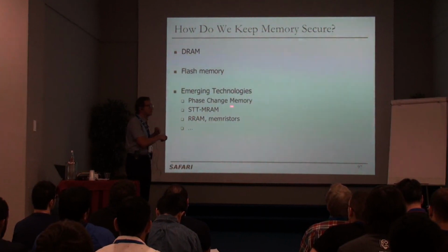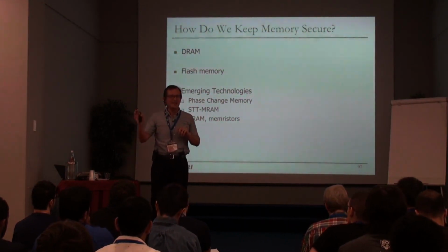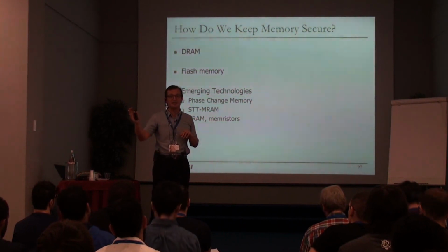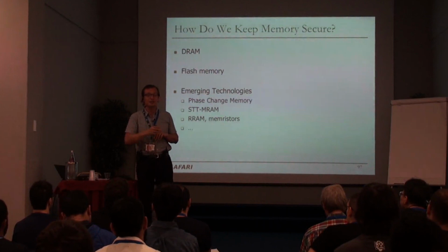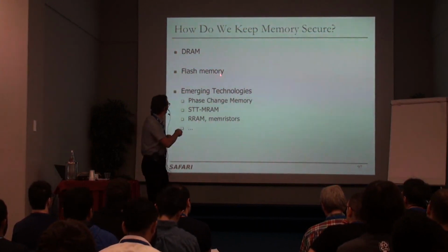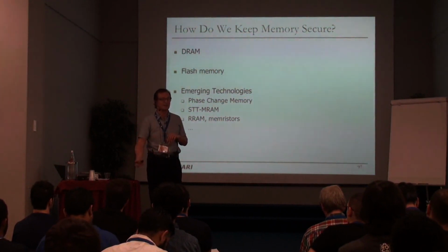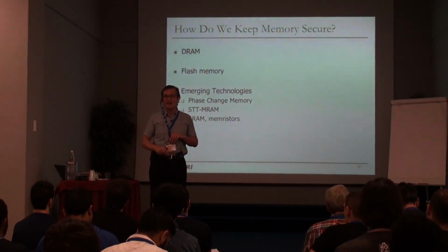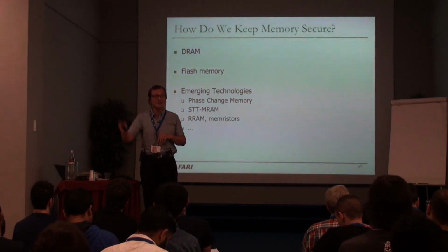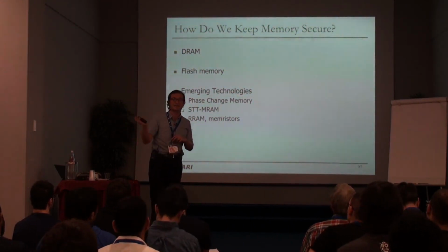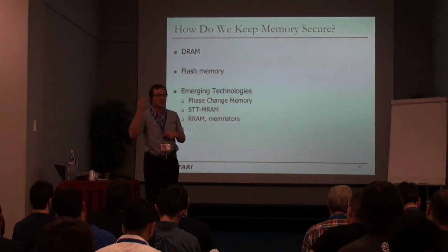You can say, oh, I don't need to refresh phase change memory. Think again. Actually, these are resistive memories, and resistance shifts over time. As a result, you actually need to refresh. Flash, very similar. It loses charge as the flash cells wear out. You need to refresh. And as flash becomes closer to the end of its lifetime, you need to refresh it very frequently. Maybe not every 64 milliseconds. According to our results, you need to refresh it maybe every 3 hours or so.